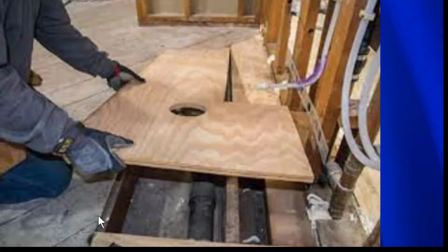And what that would do is connect the two together, because earthquake forces are coming out this way, they hit the nails, the force in the nails goes into this piece of wood, and then from that piece of wood into the nails that are attached to the plywood, and then it continues on and transfers to where the foundation is.